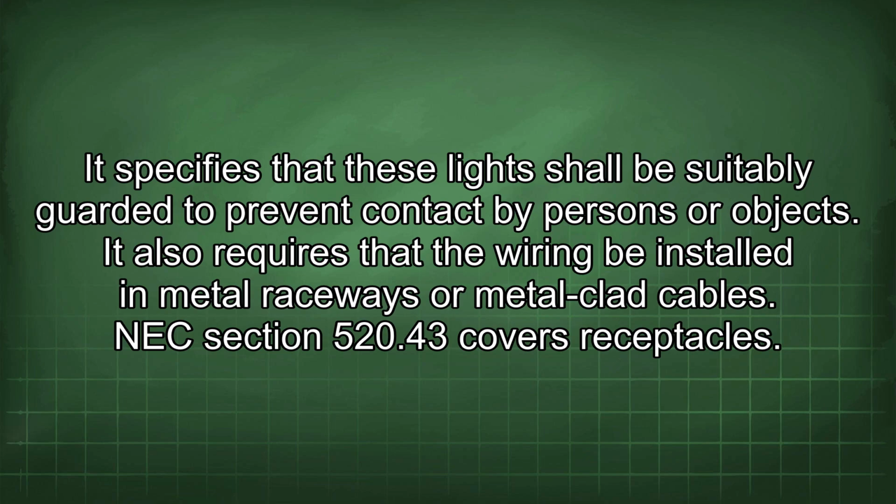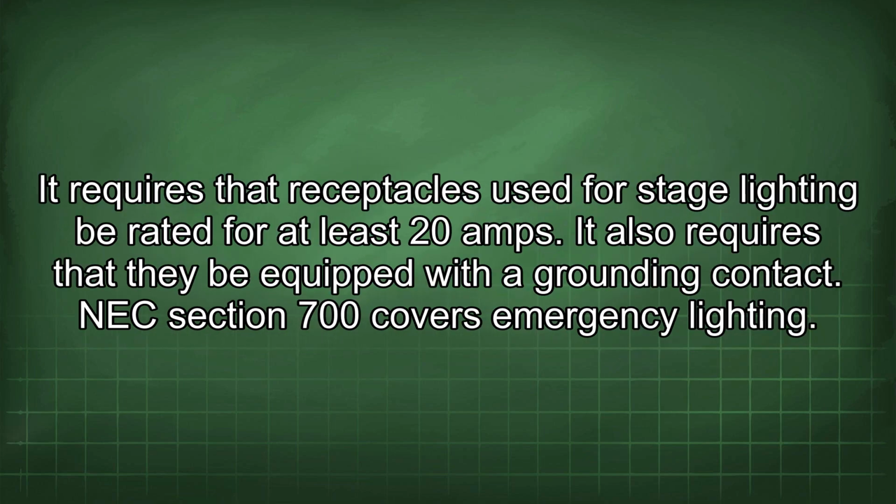NEC Section 520.43 covers receptacles. It requires that receptacles used for stage lighting be rated for at least 20 amps. It also requires that they be equipped with a grounding contact.